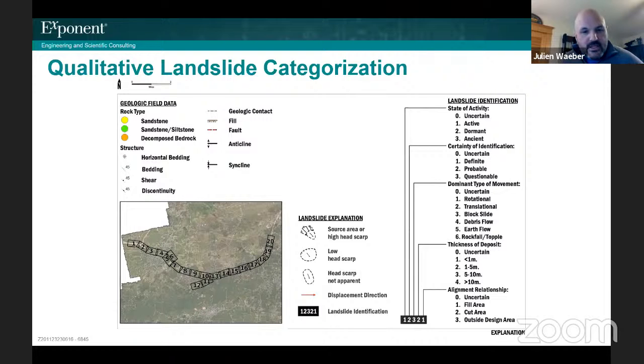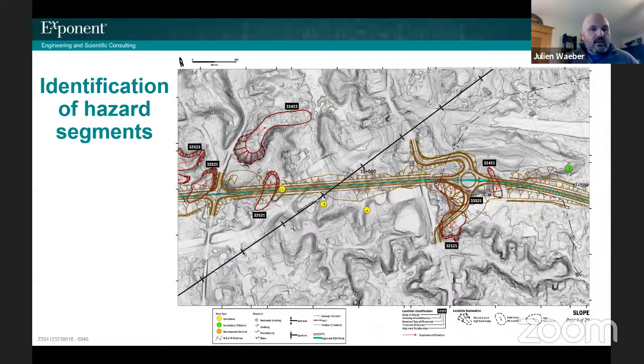And as Professor Hutchinson mentioned previously, you can apply a tremendous number of different remote sensing methodologies. And so I showed you my research, which was InSAR measurements of ground surface deformation over time. This is simply a very high resolution LiDAR imaging of the ground surface. And what you can see here is immediately you can point out areas of potential landsliding. And then based off of the categorization of the road alignment in the first place and different parts of the alignment, which might be more important than others, you can then go out to the site and either verify or do more detailed investigations, or you can simply account for them in your road design of road cuts.